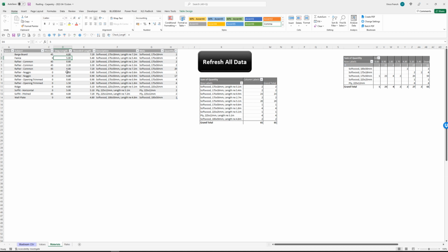Noggins, they were about 500 mil on plan. Some were slightly bigger than others. So maybe I should have taken a bit more time to mark these up, but if they were 500 mil on plan and we only added 100 mil to each end, that would work to a timber size. But if they were 510 mil, 520 mil, we've done these rounded up into every 100 mil. So that means I need to add 100 mil on, make 700 mil, so that the available size is 900 mil. Hopefully you can follow all that's going on with that, but this gives us a cutting list as well.